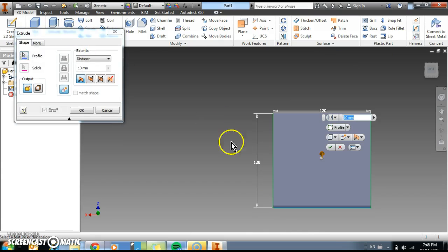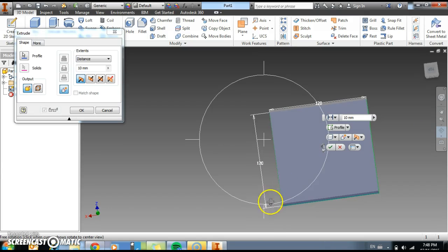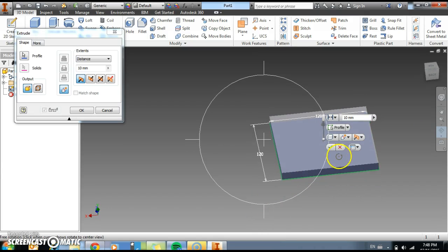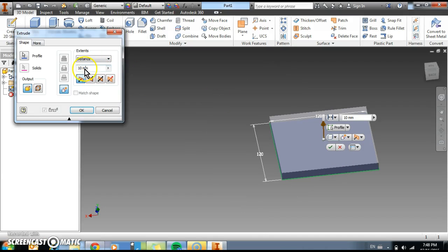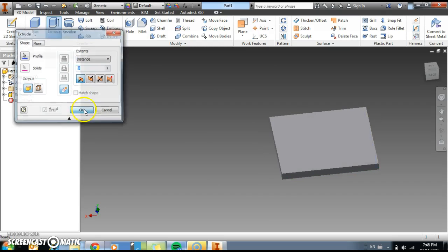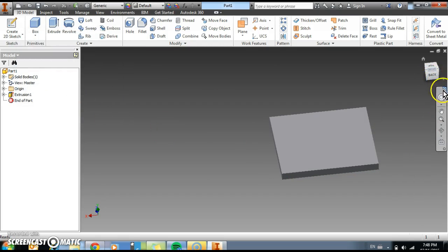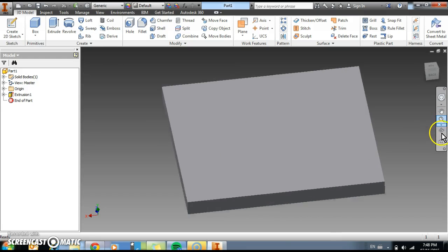Now we're going to extrude that and add volume to it. Now because that's the only shape on the page, the computer already knows that's what we want to add mass to. And so the thickness of the MDF wood we're using is 9mm. So I'm going to type in 9 there. We press OK, and there's our part. And then we're just going to bring that to surface.